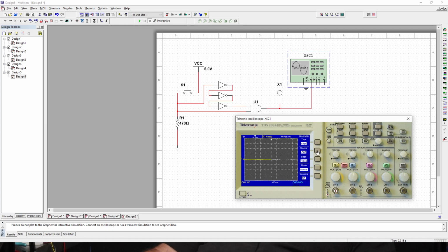We can select channel 1, 2, 3, 4, or external, but we're going to keep it on channel 1. If you select the level of the trigger, we're going to make it just a tiny bit above 0, which should bypass all the noise so we don't get false triggering, because we're capturing a single shot, the pulse. 10 millivolts, that's good. We're setting up a threshold, so ignore anything below 10 millivolts.